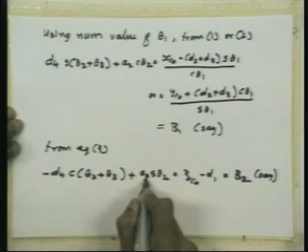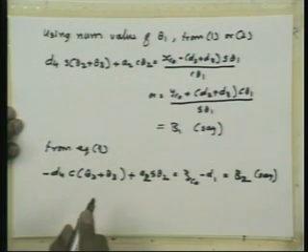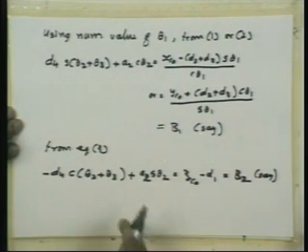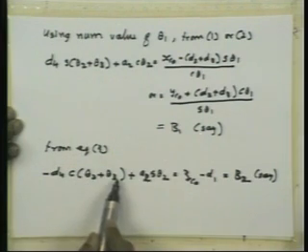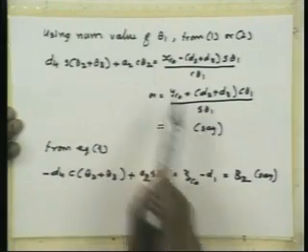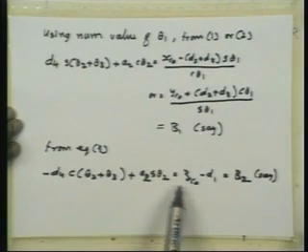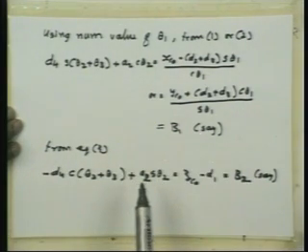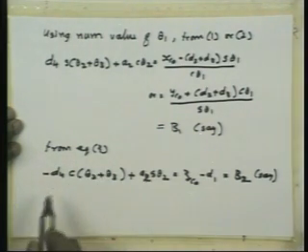This is a2, by the way, sin theta 2, fine. Now we can eliminate either theta 2 plus theta 3 or theta 2, one of them. What we do is, let us eliminate theta 2 plus theta 3. That can be done by transposing a2 cos theta 2 to this side, a2 sin theta 2 to this side, squaring and adding. You eliminate this theta 2 plus theta 3.